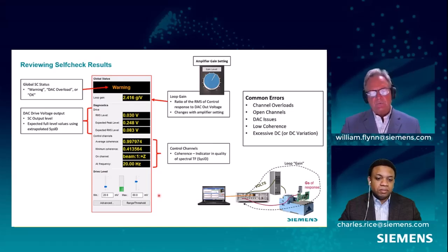Yeah, you're right. If you've done vibration control tests out of the box, those are pretty low levels. So you want to kick those up a little bit to get a good transfer function, which means you'll also get good coherence values. And in fact, typically I would just look at these. That's a good indication of a good quality self-check, good system check, looking at coherence values.